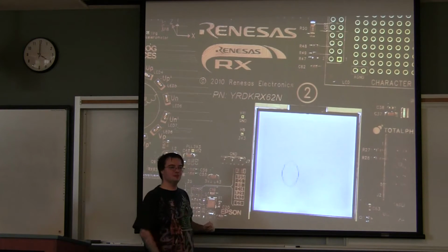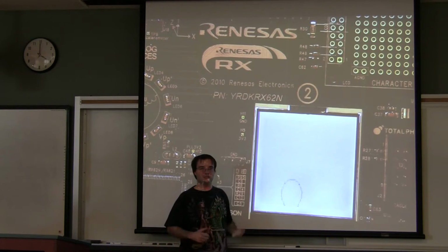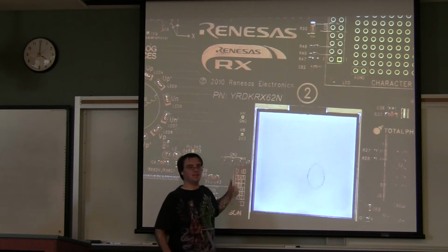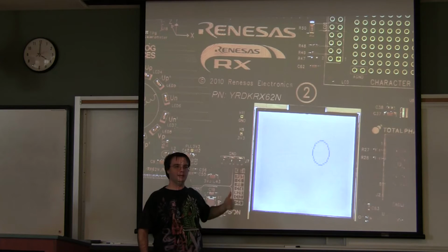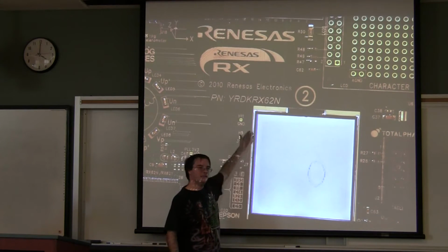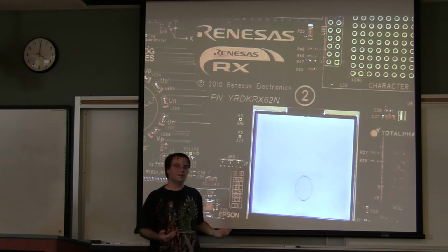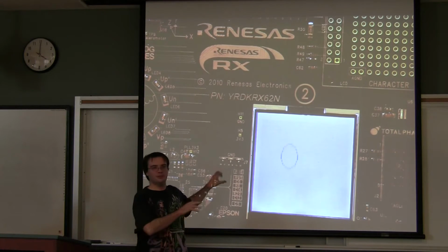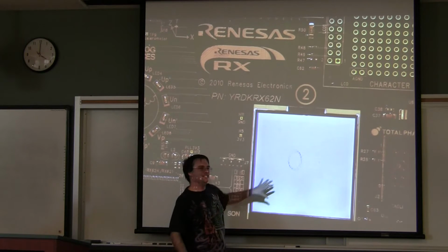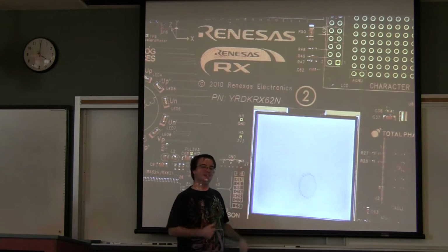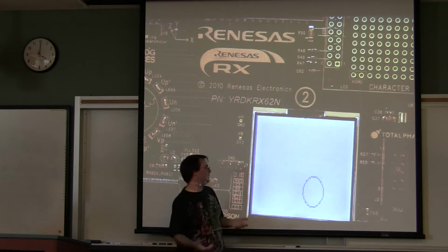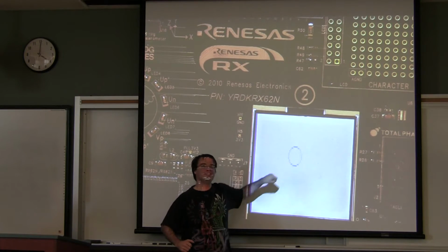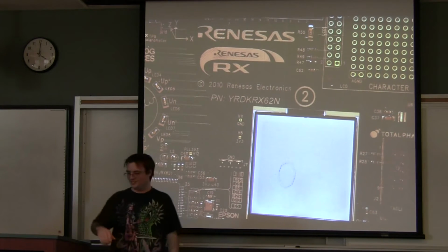There's a quirk with this LCD screen where if you try to render a pixel at a particular offset, it skips down in byte increments, so it skips by 8 pixels on the y-axis. In this lab we talk about that and how to get around it. So not only are we interfacing the peripheral, we're also fixing this little flaw from Lab 2 and learning how to actually render a circle. This is actually a dynamic font, so we're playing with fonts in this lab as well.